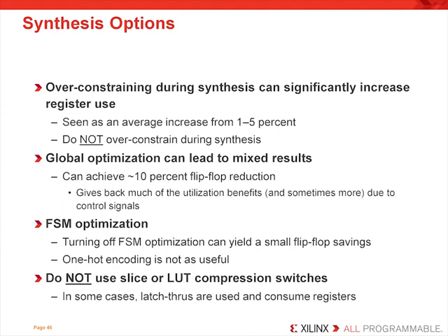Since we've been talking about registers being a premium, we wanted to take a second and mention some considerations about synthesis options. First of all, don't over-constrain your design. This means that you should not place timing constraints on your design that are, first of all, unrealistic. As we always say, place timing constraints that reflect your timing needs. Remember that unless you are operating at worst-case operating conditions, you already have some slack.